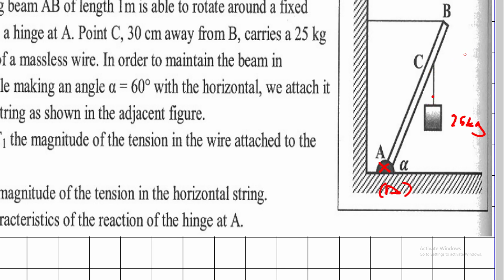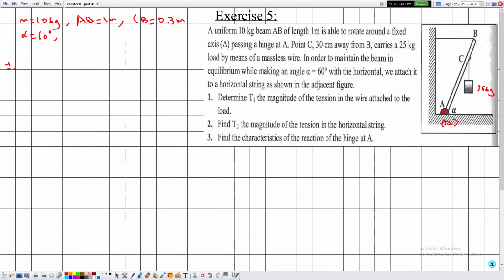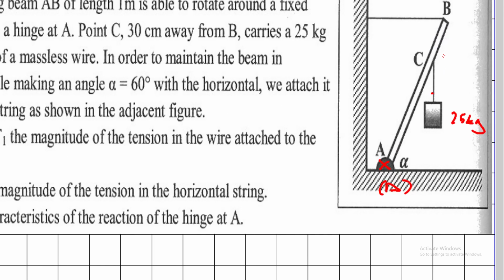Now in this case, because we are interested in this tension, here we have two tensions. We have the tension T1 like this, and we have the tension T1 prime like this. And because we know that this string is inextensible, they are equal, but no need to consider all the system. We can consider only the system which consists of this solid and this string in order to apply the condition of equilibrium to determine the value of T1.